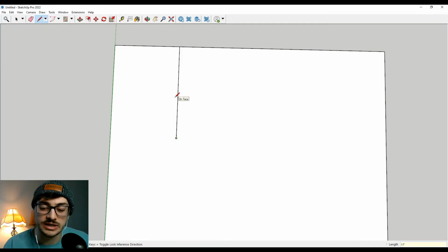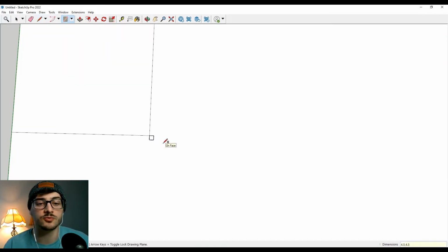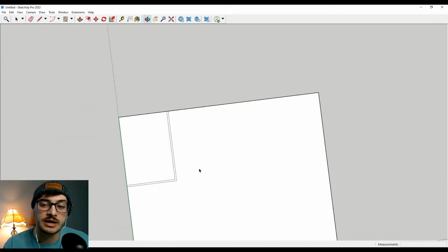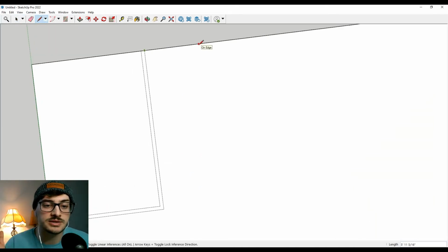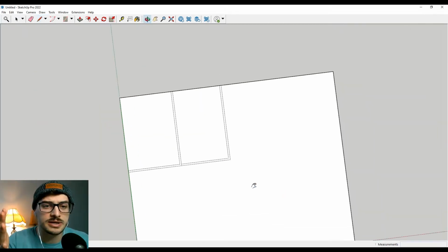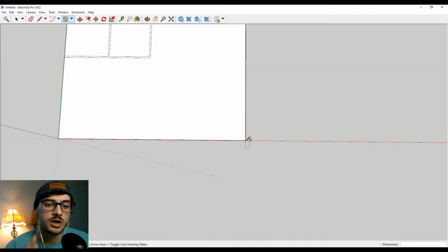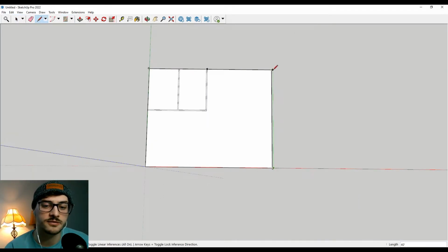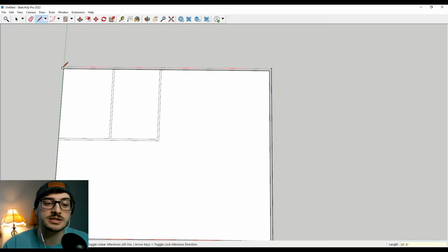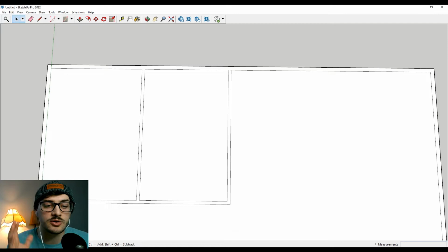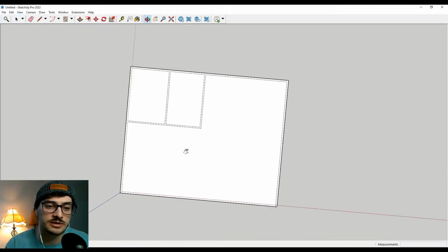So to get started, even though it's a 3D model of a house, a really important step is creating an accurate 2D floor plan. This is super important because you can't just start by creating a 3D area. Everything becomes more difficult to modify if you have a room size or a closet size that you get slightly off in 3 dimensions. It's a lot more work to correct than if you just make sure that you have a dimensionally accurate 2D floor plan.